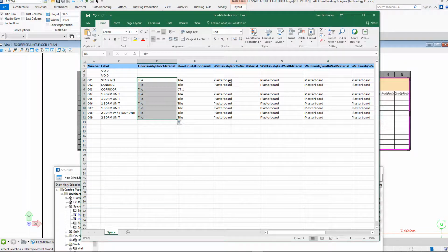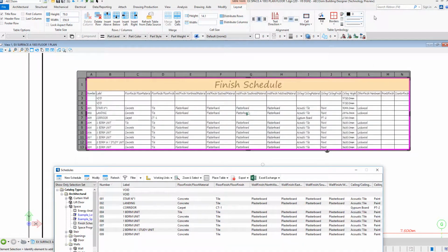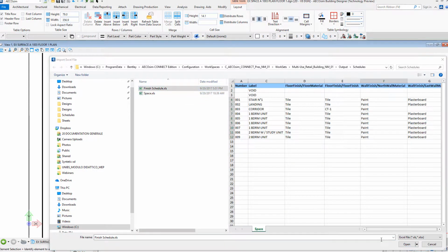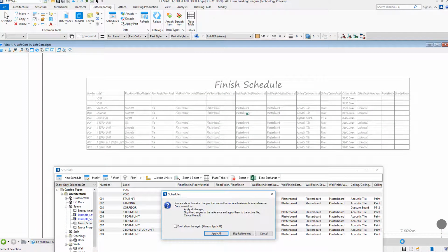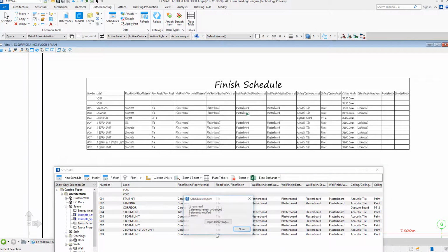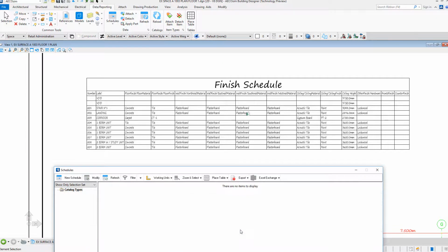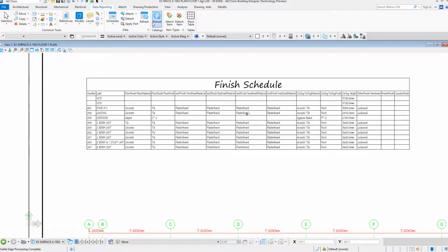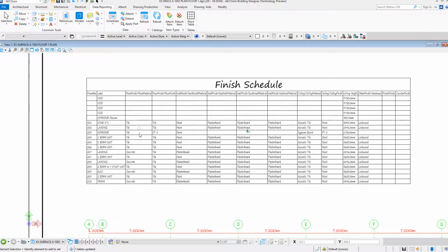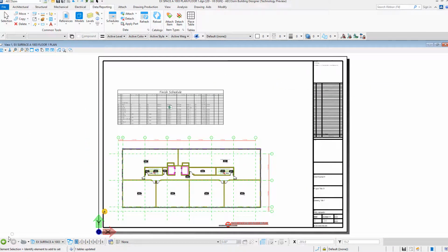What I'm doing now is that I manipulate and update the project information from the project in Excel. I'm updating information in Excel columns. After modification, I save the Excel file and I reload the changes in the project with the Update from Excel feature. The project information will be updated, and the information displayed in the schedule will reflect these changes with the refresh command. We can check the updated information in the columns of the schedule which is located in the presentation sheet.